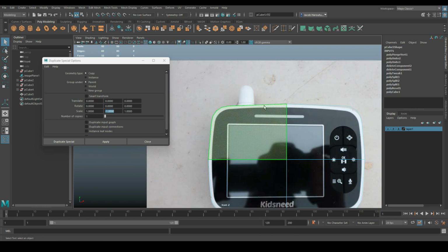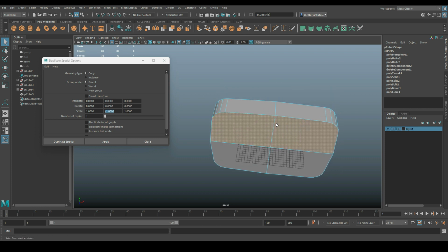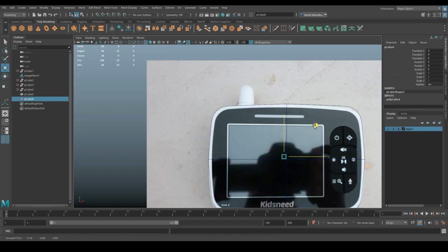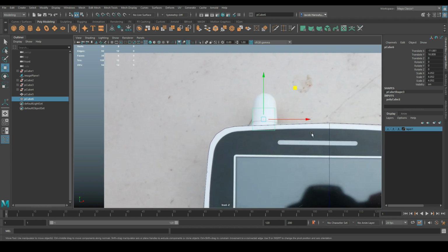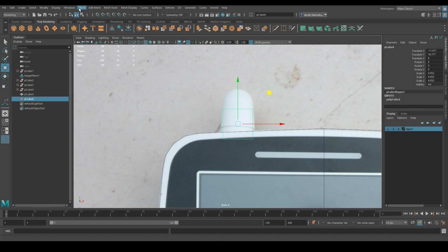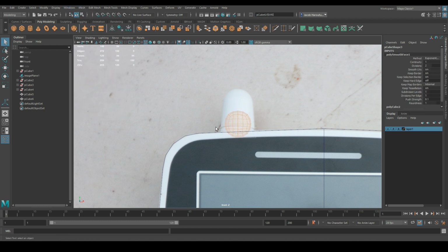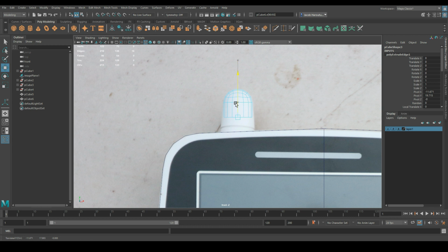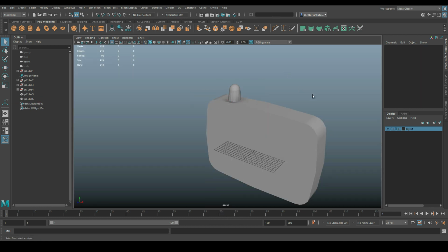And likewise, I'm gonna go ahead and add the antenna now. And to do that, I'm simply gonna bring in another piece of geometry, and I'm gonna do it by eye. This is a cube that can turn into a spherical shape by smoothing it. So now that we have this, I'm just gonna simply click Mesh, Smooth. I'm gonna do 2 iterations of that smooth. I'm gonna delete the bottom half of that, bring this up. That's looking pretty good. I'm gonna scale this and extrude it down and scale that up so that we have the makings of an antenna.